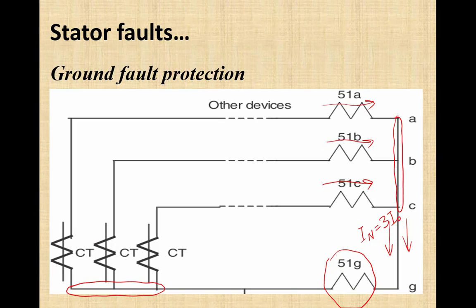So that's why the operation of this relay should be delayed, so that it should wait for the motor to start, and then if current is there after that time, that is an indication of a fault. So during the motor starting time, this relay will wait for that time, because current will be there in the residual path due to DC offset in the primary currents.